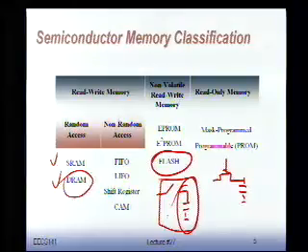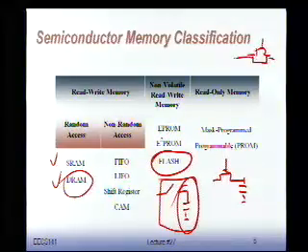larger capacitors means more area. For instance, I can create a capacitor by taking a transistor and short circuiting it, right? That's a capacitor. And I basically connect here, and I have a capacitor. Very nice capacitor because it's basically determined by the gate oxide. However, if I want to make it bigger, I have to stretch it out in a two-dimensional fashion.